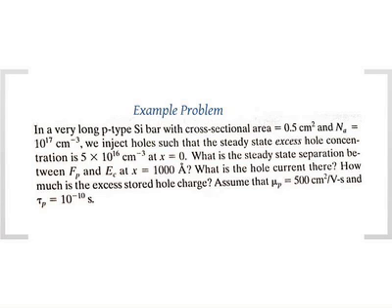First, you don't need to actually give me the answers. Tell me how we would address this. So we need to know the Fermi level. So what do we need? It's okay if you're wrong. Well, it's silicon, so we don't need the band gap. Remember, we are trying to see where the Fermi level is with respect to the conduction band. So we don't necessarily need the band gap, but we know it because it's silicon.